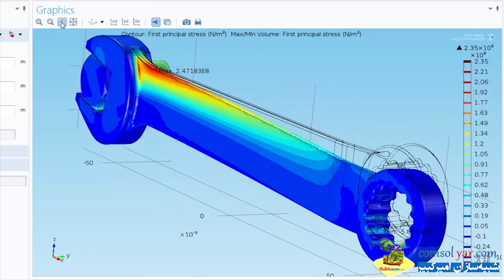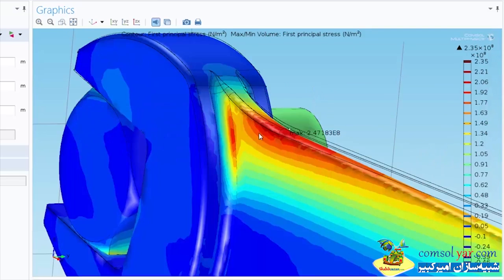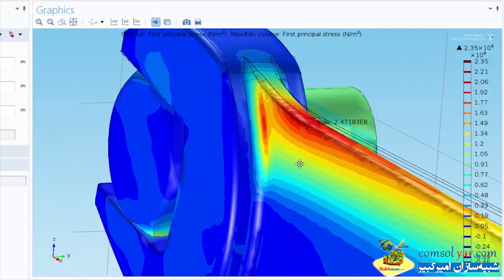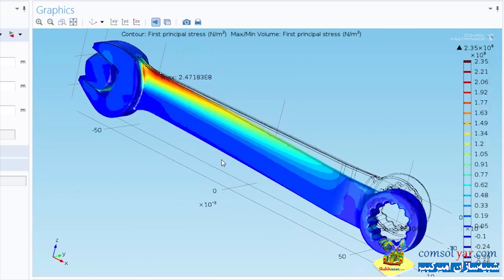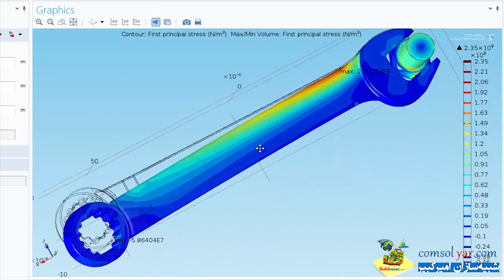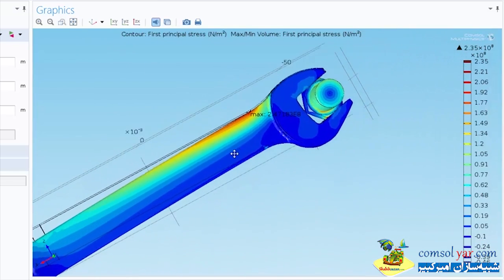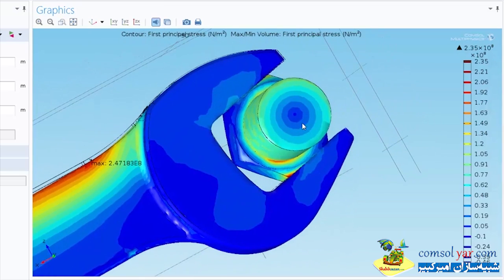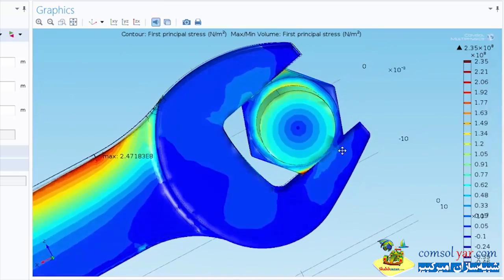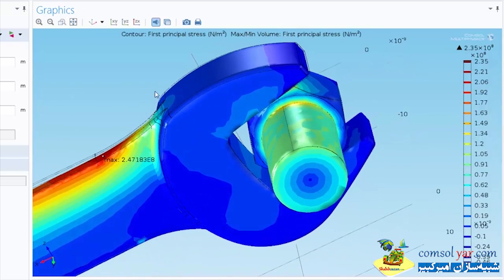This twist out toward the y-axis, around the x-axis, produces a stress maximum towards the left of the beam, which is what we would expect. If we examine the bolt, we can see that the shear stress within it grows radially, which is also something that you'd expect from this problem.